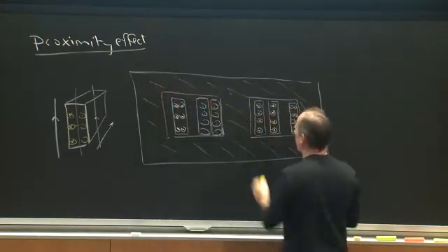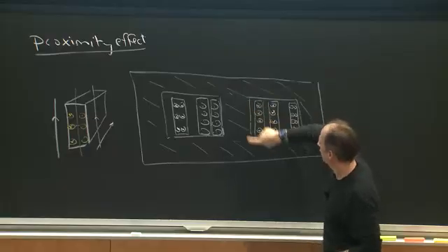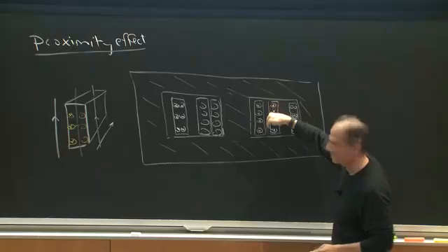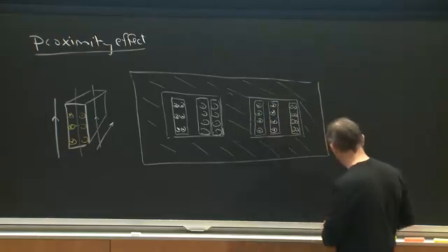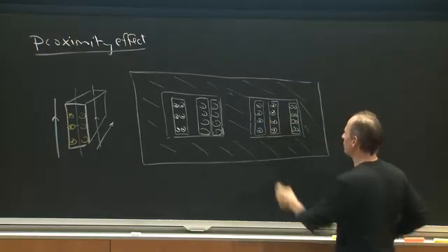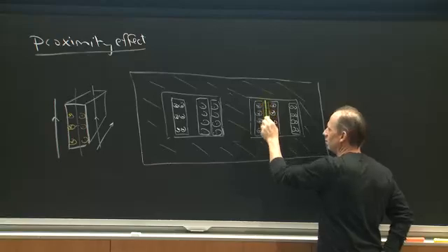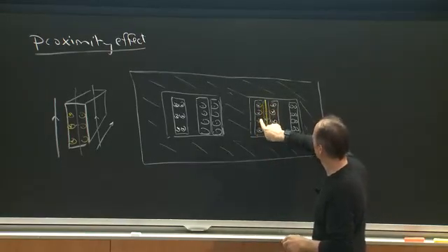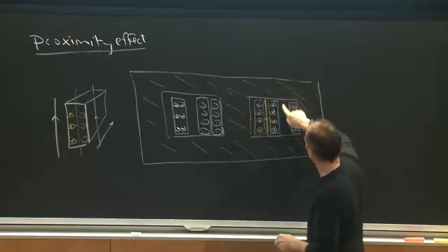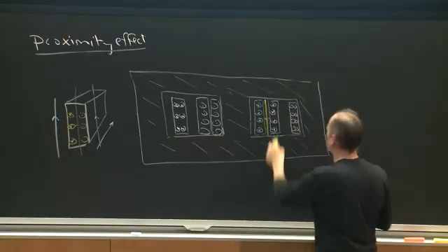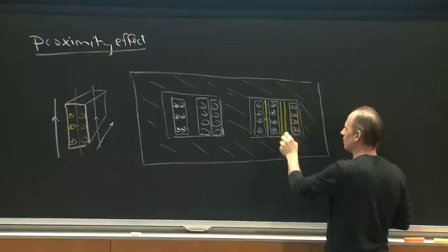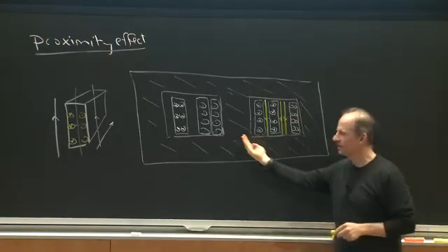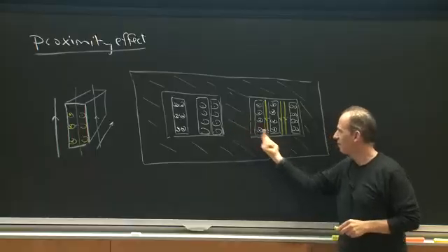So if I execute Ampere's law, integral of H dot dl around, say, a loop here, the only field that appears is in the window. And what that means is, in this picture, if I plotted the H field, I ought to have some H field here that's associated with this current from the middle. And if I looped around two layers of winding, I get two H fields, and so forth. So what's happening is I go across the window, my field builds up.